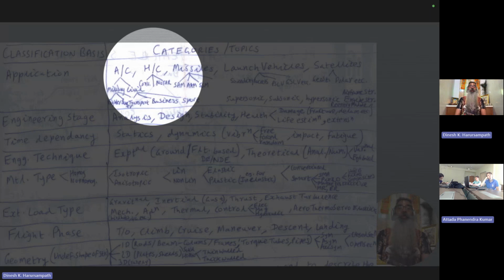So, if you want to be able to analyze these kinds of things, then you need to have more advanced models for the structures. In particular, for example, if you're modeling this as a cantilever, you need to take care of the initiation of that delamination and then the growth of the delamination, how the stiffnesses are affected, and therefore how the overall failure occurs. Because these are so critical that sometimes they can be quite disastrous in terms of how the overall flight happens.